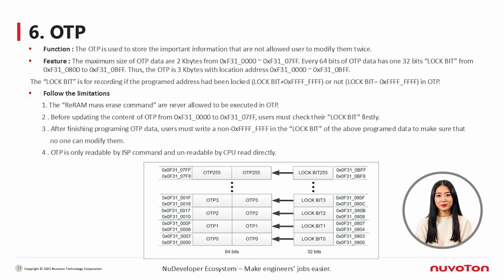For example, when lock bit 0 is not 0xFFFFFFFF, OTP 0 cannot be programmed again, regardless of whether its content is all 1 or not. The following principles need to be followed in the application. 1. The ReRAM mass erase command is never allowed to be executed in OTP.